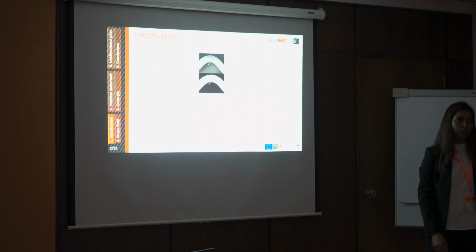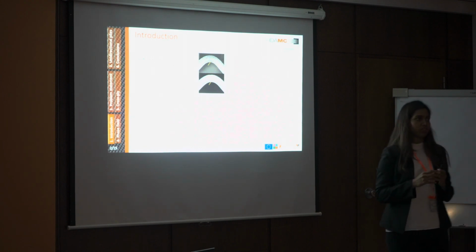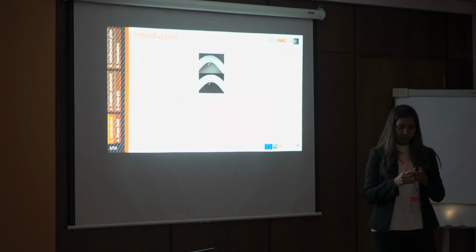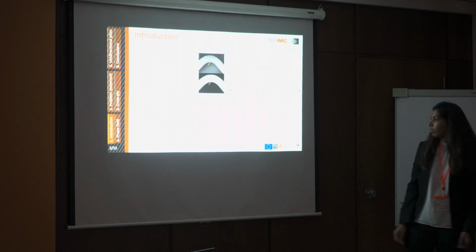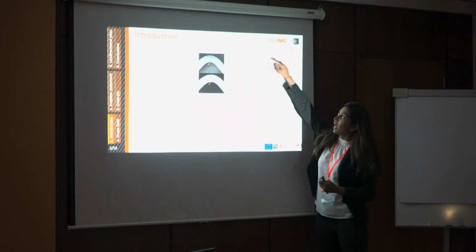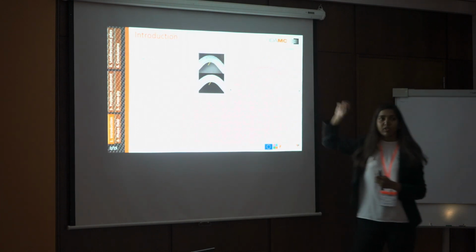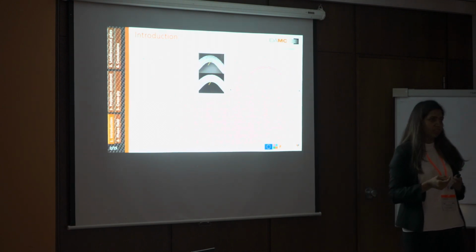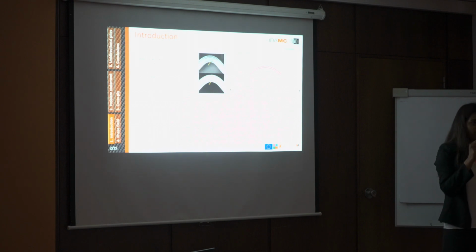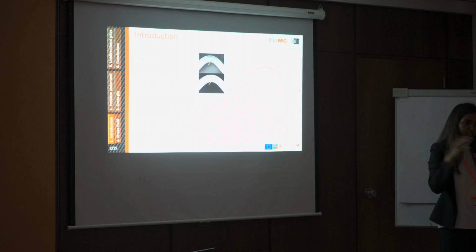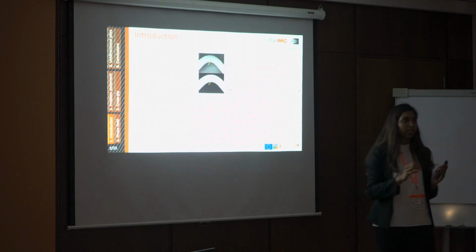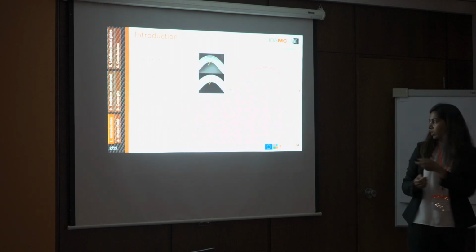So there are basically two types. One is traditional unfolding, which is a classical failure mechanism that occurs in unidirectional curved composite specimens. When we apply the opening bending moment, there will be high stresses in this curved region, and when the stresses in the thickness direction reach a maximum value, that is the interlaminar tensile strength, a crack is initiated in the interlaminar direction and then propagates to form a delamination. So that's the traditional unfolding failure, which is governed purely by the interlaminar, out-of-plane properties.